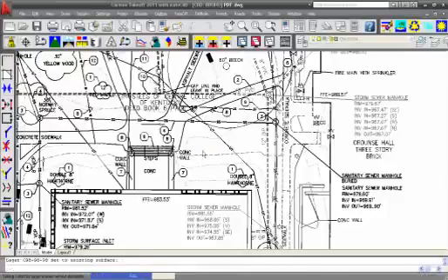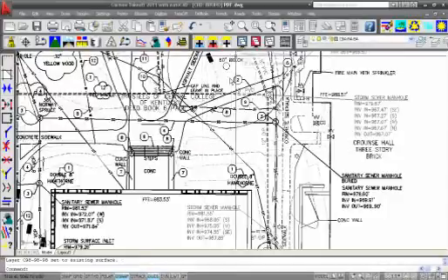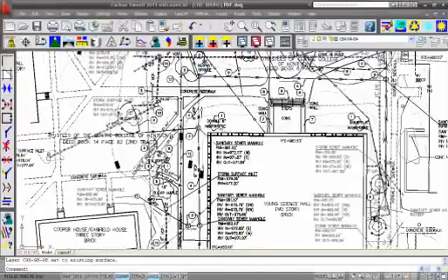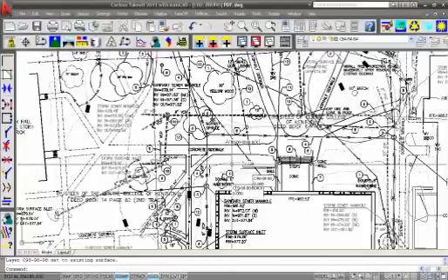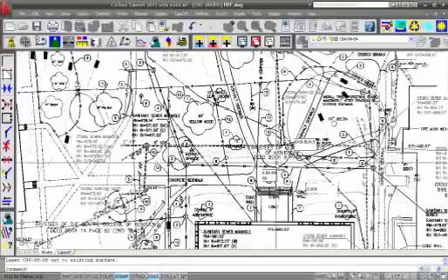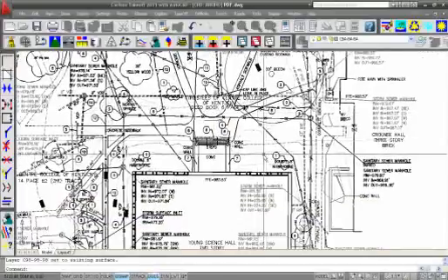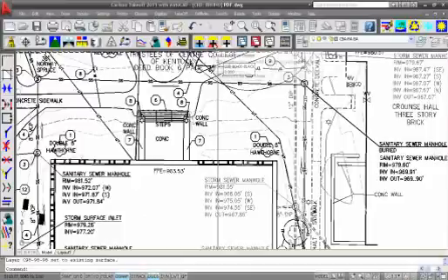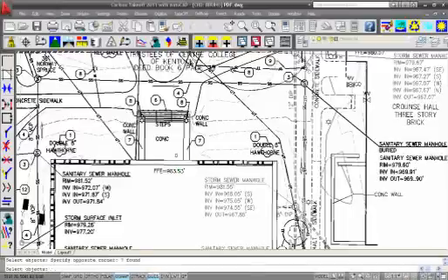Now, how did you know that was the existing? Was that through drawing inspector or? Yeah, just looking at the drawing, these contour lines look like existing contours. You know, they're not going through the building, and it's just kind of a judgment call that I'm calling these existing contours. Because obviously from that file we need to find out what the existing is and what the proposed is so we can get the differences. Right. So it's important we find which layers, which line work is attributed to which file format, whether it's existing or proposed. Right. Okay. Yep.